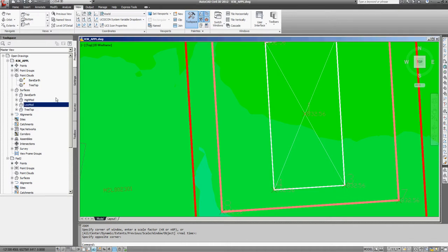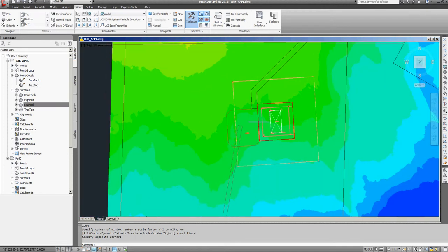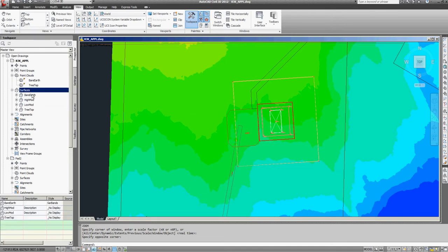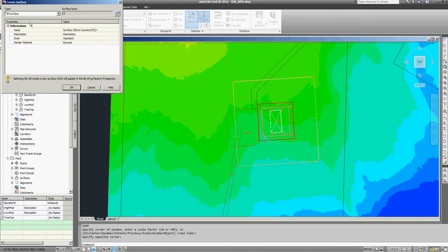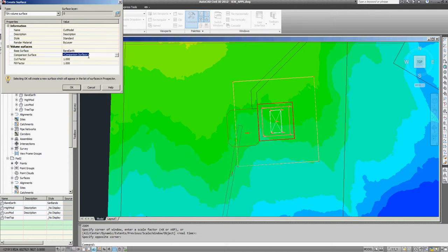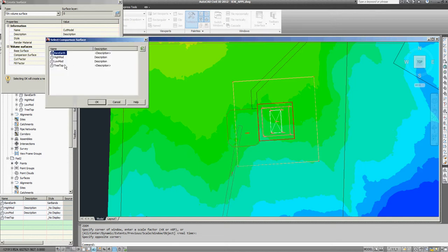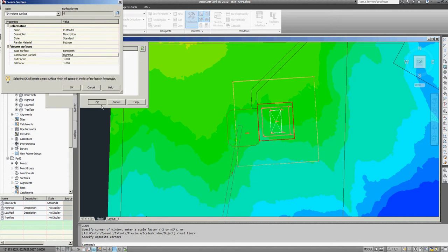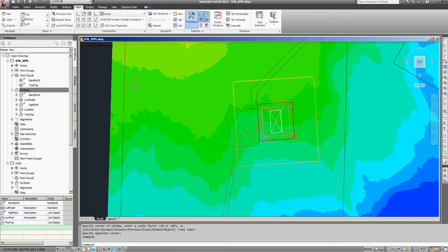And then, of course, now that the well is up at the correct place, what we simply have to do is create a deviation surface showing what the cuts and fills are. So to do that, we'll create a new surface where we compare the cut model, the difference between the bare earth or ground with our well site model. So for example, in this case, the model where we go into the cut. Okay, it calculates some things,